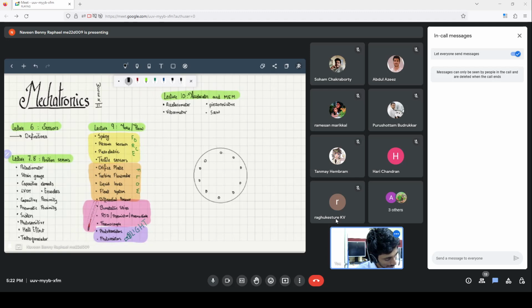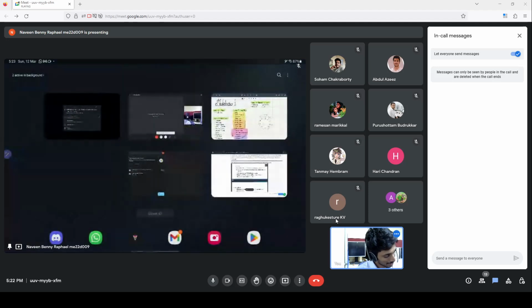If you shine light through these holes and have a light sensor on the other end, you can just keep counting the number of times light has shone on the sensor, then you'll be able to get at which point the wheel is right now, as the wheel is rotating. The slides explain that in general we actually use 3 holes instead of 1, and that makes sense, because this is easier to show in the diagram.